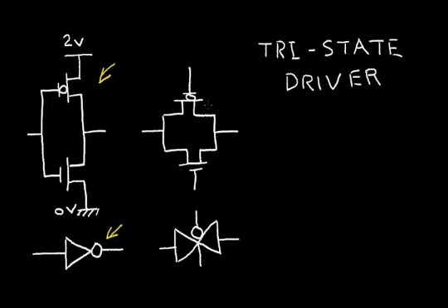And we also talked about the CMOS switch, where this is the symbol for the CMOS switch. And we explained that the inverter takes whatever is at the input. If the input is at a high voltage, the NMOS transistor is on, the PMOS transistor is off, and we're at a low voltage. So it takes the input. If it's high, it makes the output low. If the input is low, the output is high.